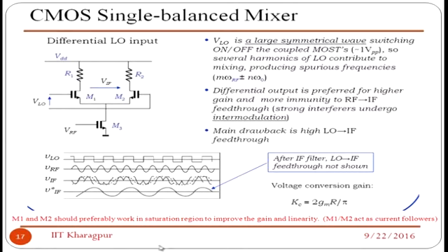Because of this square law, you know this problem. Typically the gain of this is very easy to calculate, because this is my switching, mind it. This is not going to affect my gain. The gain is mainly here, the change in the transconductance. So gm times RL is my gain.